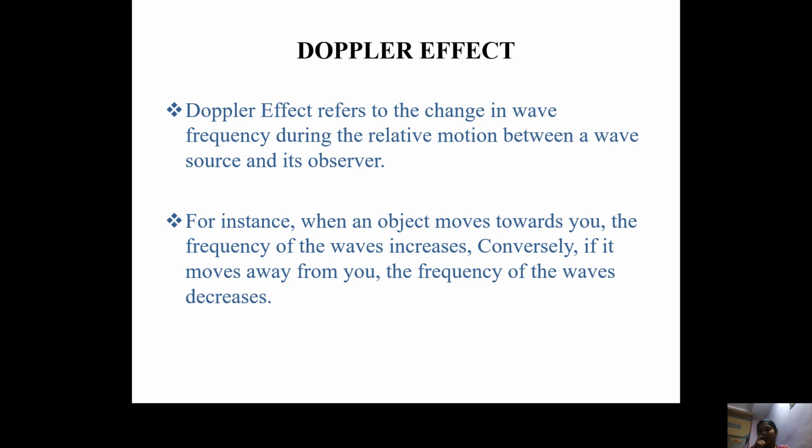When you are observing from the receiver side and the target is approaching towards you, the frequency increases. Here we have to add the difference frequency, which is nothing but the Doppler frequency, to the signal frequency which we have transmitted. For example, take Ft as the transmitted signal frequency.